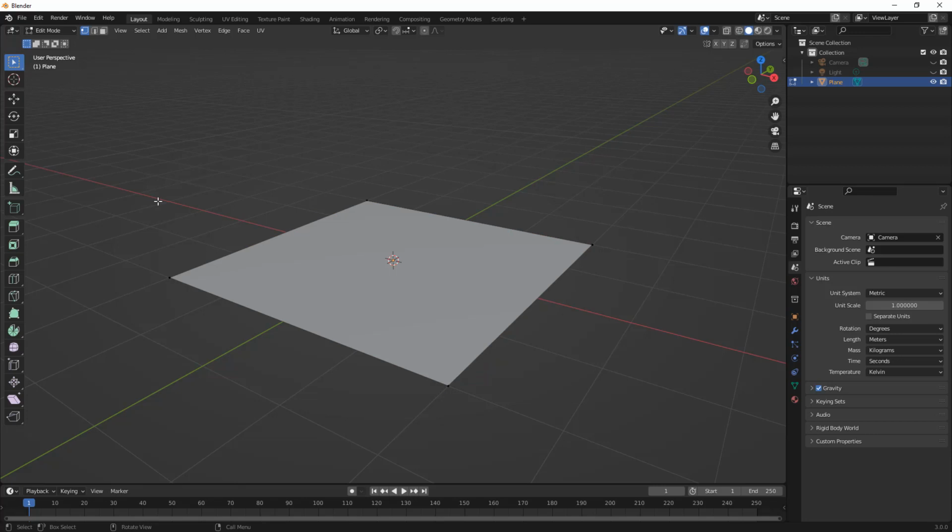So the first thing that I want to focus on is going to be the selection process. When we select a single vertex, this is something that we covered in the last video, there are ways in which we can create an instance or a selection as we go around the object. So holding down Control or Command and then clicking another vertex will allow us to pick the shortest path. And just like when we inserted the plane, another dialog appears. Notice that we have some options for face stepping, topology distance, and fill region. We have deselected, selected, and offset. And these values are going to be different depending on our selection.